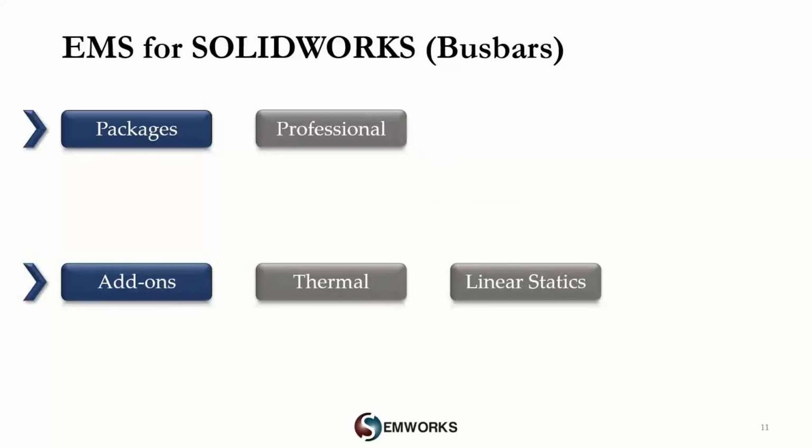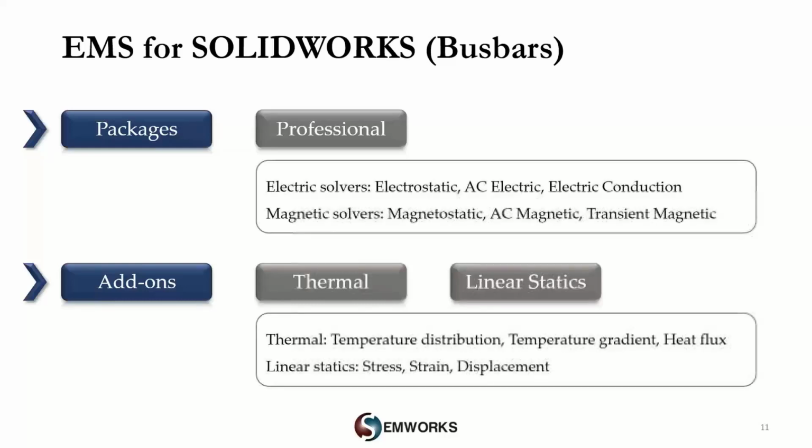To perform electromagnetic and multiphysics analysis of high-power bus bars, the EMS Professional package with thermal and linear statics add-ons should be used. The electric solver can be used to compute electric fields and current density distribution, while magnetic solvers can be used to compute magnetic fields and losses. Thermal analysis can help a user to study temperature distribution, while linear statics can compute stress and strain results.